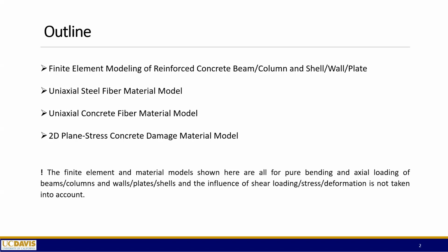If I may just say, this is really important. All these fiber elements and all these elements that have plane stress for shell, wall, and plate really rely on just pure bending. If one wants to go to some influence of shear, of course you can go to Timoshenko beam, but in that case it's not nonlinear. What I've seen people mostly do is use solids to model both beams and shells and plates. So with that caveat, this is for pure bending and axial loading, and this is rarely mentioned when you see results of this kind. Anyway, I'm sorry. Go ahead.